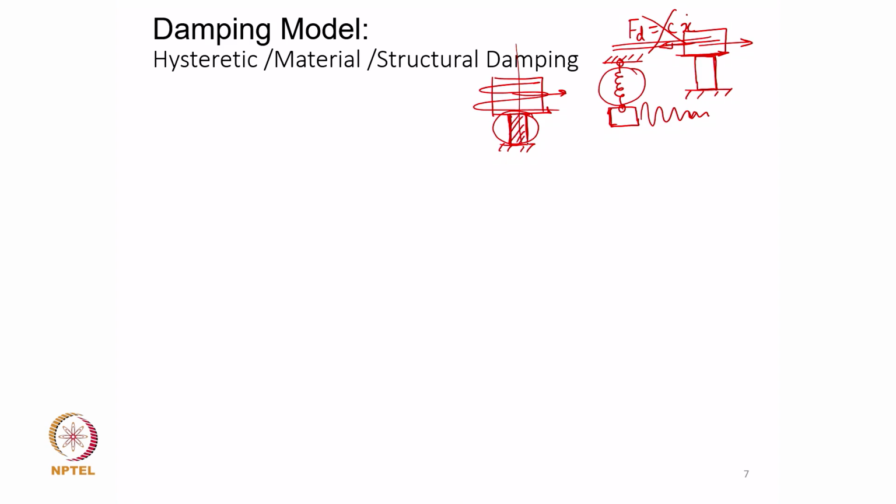the same unit, the same mount or isolator, is also going to act like a spring, because as this particular mount deflects laterally as the mass moves laterally, it is going to generate a restoring force to bring it back to its mean equilibrium position. So, the same mount acts both like a spring as well as a dashpot. So, it makes sense to write the restoring force as Fr. This restoring force Fr is generated as the mass tries to move given an initial disturbance. So, the restoring force because of the springing action of the structural member, which is a mount,